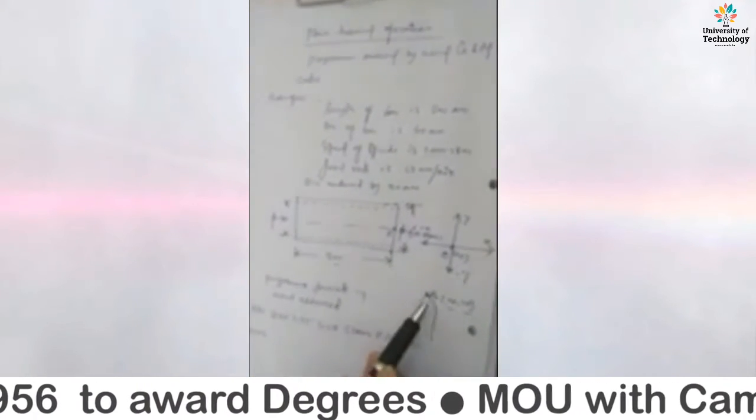point to point and rapid traverse, that we can use G00, and X and Y coordinates we put 20. And next line again G00, X 0 and Y 0, and the spindle we can start with M03, and in line 4 put G01 and start the operation.